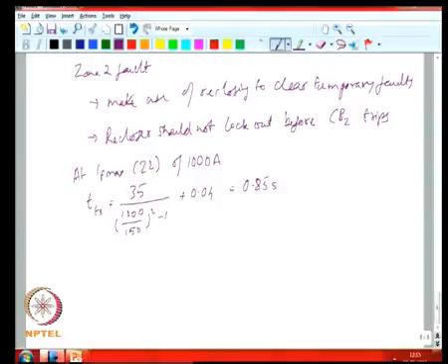of 0.85 seconds, and if you look at your T naught duration of 0.1 seconds, then this corresponds to the breaker advancing by 0.1 divided by 0.85, which corresponds to 11.8% of your trip time for the circuit breaker.